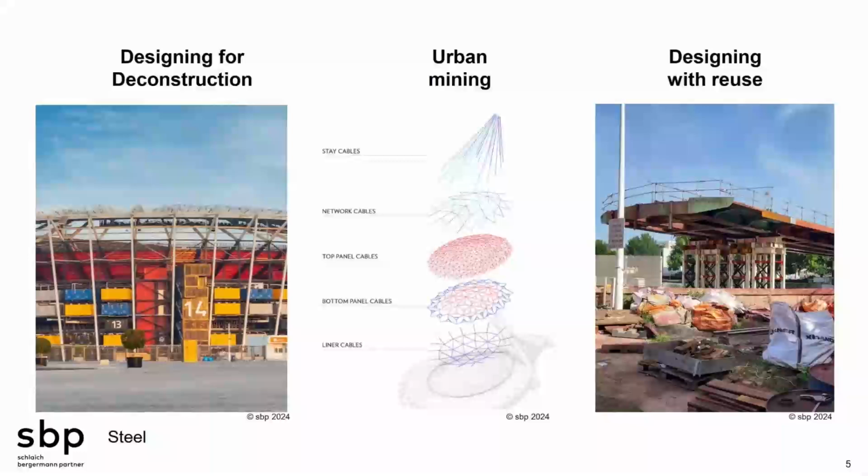We could use more normal testing processes that structural engineers and builders are comfortable using. This is really great for structures which haven't been subject to plastic deformation. So seismic is no good here necessarily, and also fatigue. So rail and road bridges are some of the few structures that are probably not so good for reuse of steel. Go to the next slide.